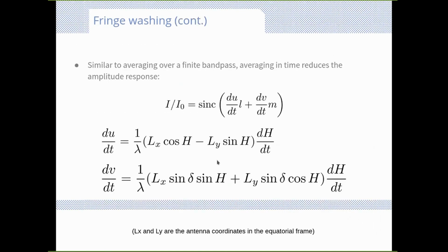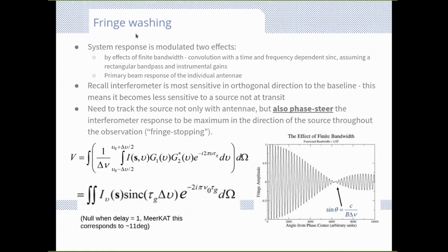Okay. Fringe washing is what I've just referred to. This is the drop in amplitude that you get from averaging over time, for some integration period. The other part of the fringe washing comes from averaging in frequency.